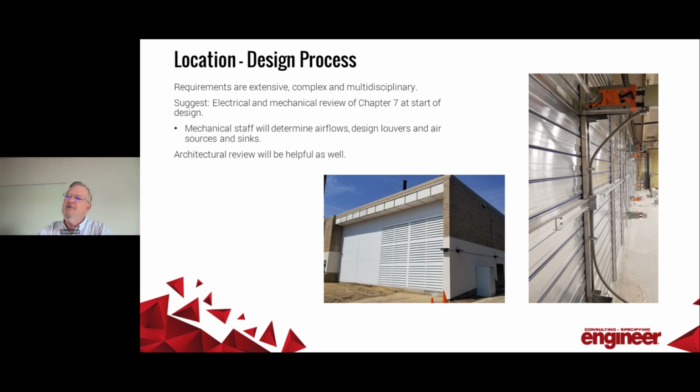We're going to talk briefly about the design process for the generator location. The requirements for the EPS location are very complicated, and they run across multiple disciplines. It can be real easy to overlook something, and it can be very costly to correct those deficiencies after construction in the field. It's worth taking time to review the generator location with the mechanical design team, and if you can, persuade the architectural team to show up with them as well.